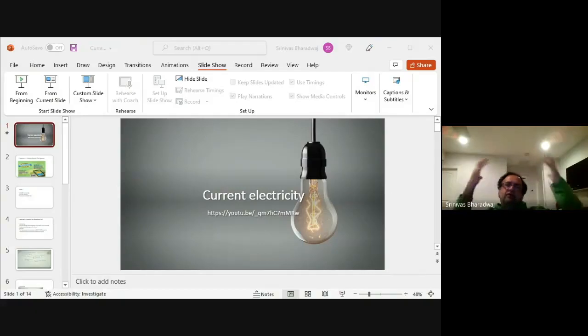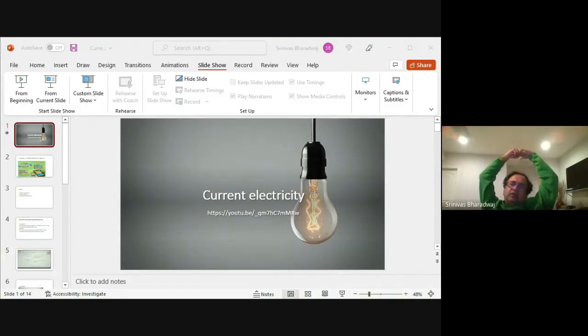Otherwise, you will have a lot of unknowns, a lot of variables, and then you will have to use Cramer's rule or something and it becomes very, very difficult. So he uses the junction rule to reduce the number of unknowns. He has only two loops and two unknowns. The third unknown he solves using the junction rule. So I3 is I1 minus I2. Look at the convention for I3. Now he's going to write the equation.